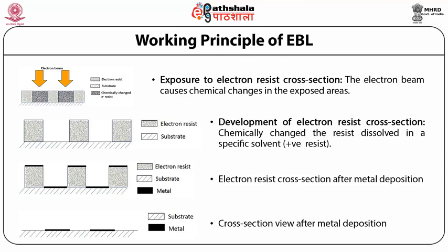After metal deposition, the remaining unexposed resist is dissolved in an aggressive solvent for lift-off. The metal sticking to the resist loses footing, and only the metal sticking to the substrate remains after the lift-off process, as schematized in figure 6.